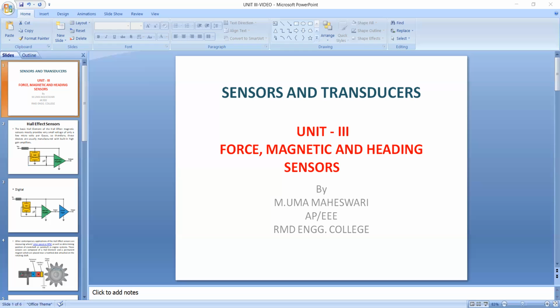These digital output sensors are widely used as limit switches in three-dimensional printers and positional interlocks in automated systems. As an application, the Hall effect sensor is used for measuring the speed of the wheel or the speed of the motor by determining the position of the crankshaft or camshaft in the engine system.